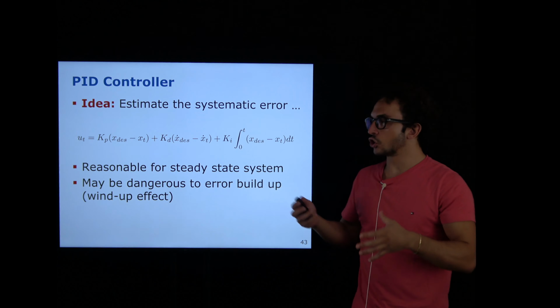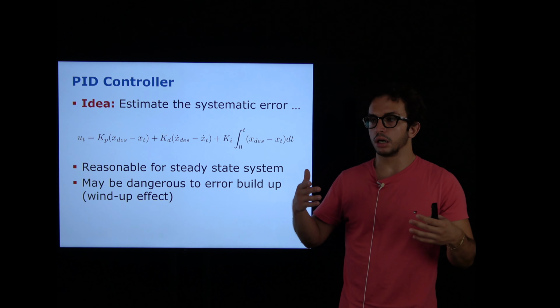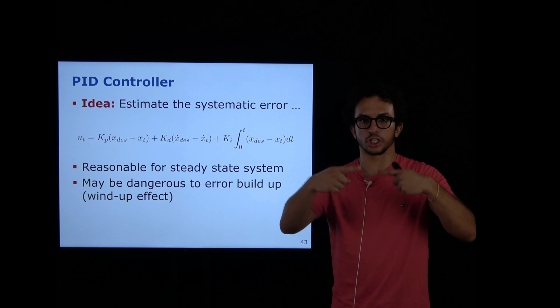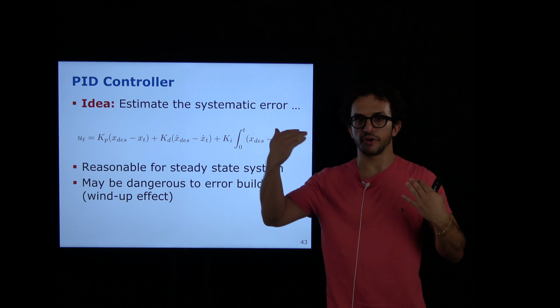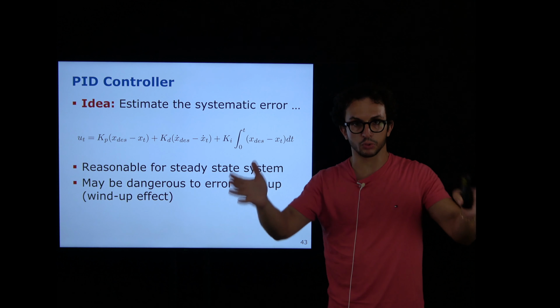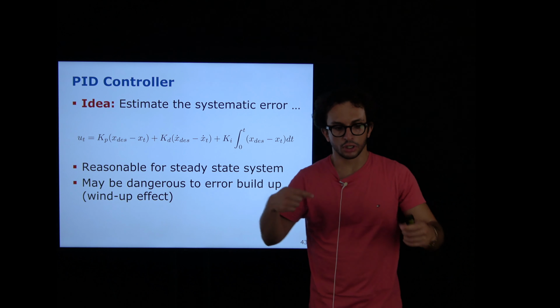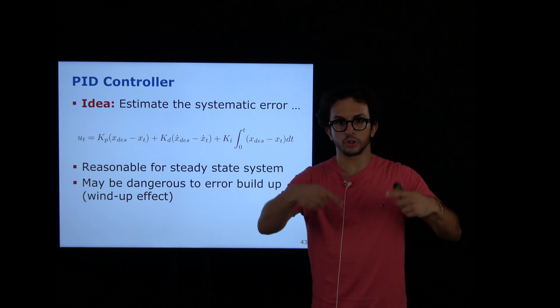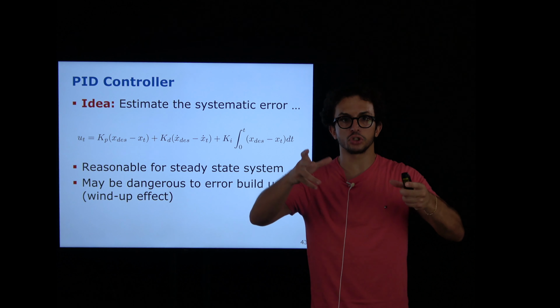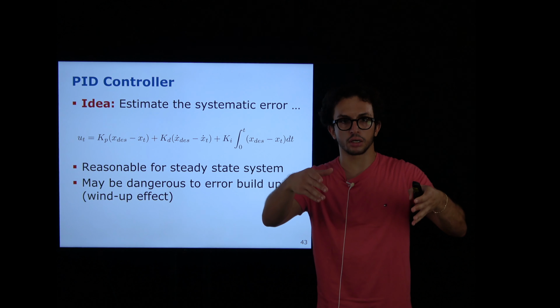And since this is growing, errors keep adding up, and the integral term starts charging and charging and charging, and it becomes something very, very big. So this actually hits all the saturation, windup, everything that we mentioned before. Now imagine that at some point, the wheels keep turning, and they manage to unstick. And so the robot is now back on track.